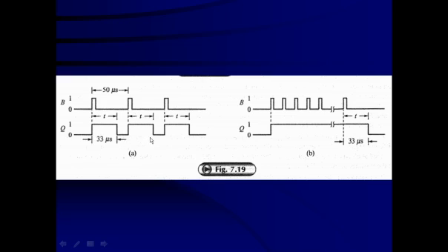But if the clock pulses which are given are spaced by 10 microseconds, then after 10 microseconds, the second trigger pulse will be there. So before it times out, that is 33 microseconds, it has already obtained another trigger pulse. So it will be re-triggered and it is going to continue, and the output remains in the high state until the last trigger pulse.